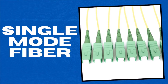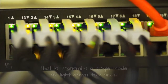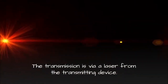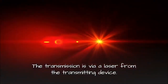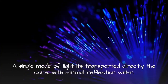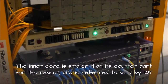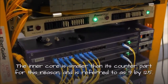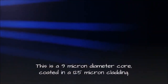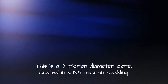Single mode fiber. The terminology of single mode fiber comes from the fact that it transmits a single mode of light down its core. The transmission is via a laser from the transmitting device. A single mode of light is transported directly down the core, with minimal reflection within. The inner core is smaller than its counterpart for this reason, and is referred to as 9 by 125. This is a 9 micron diameter core, coated in a 125 micron cladding.